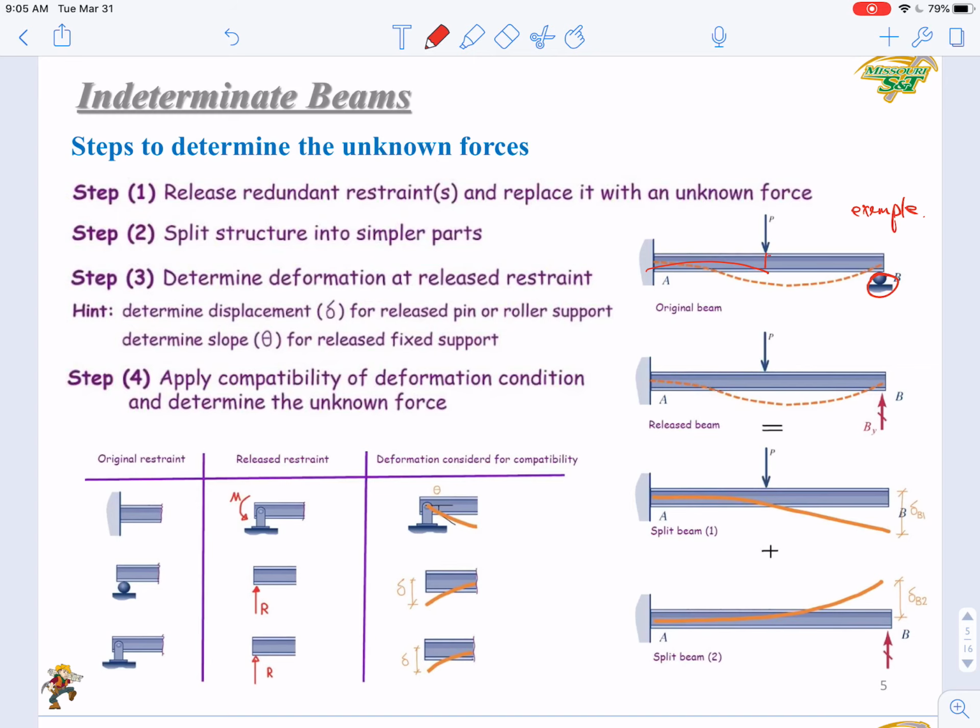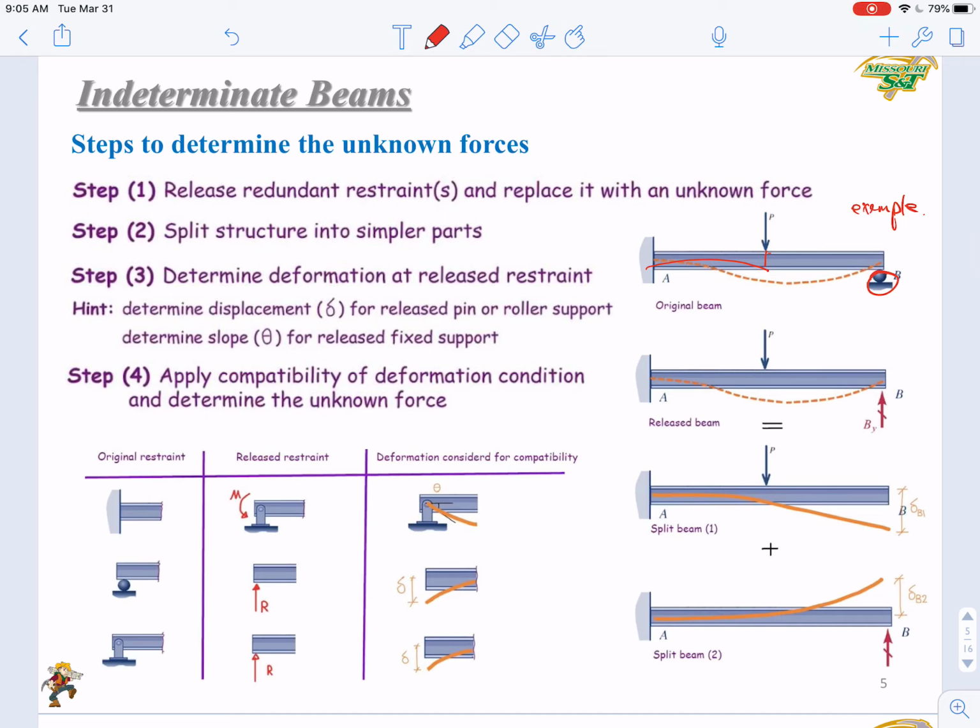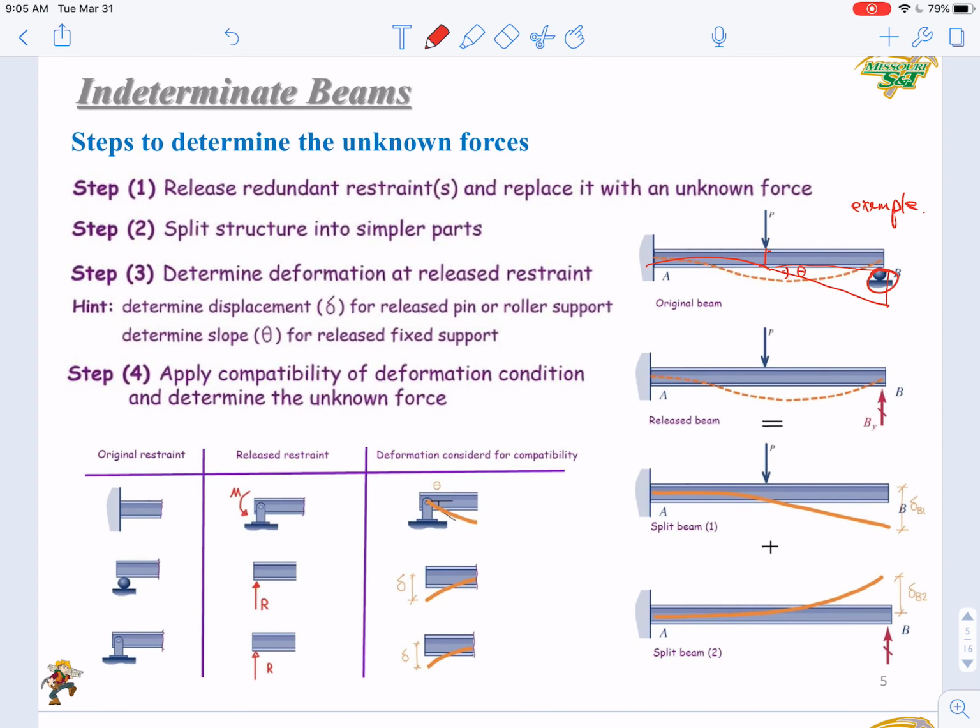Then this second part will be keeping straight. So you will get an angle. So you just calculate the slope at this point. So you can calculate even the deflection at the free end. Right? This is based on our previous 2 lectures. So you can solve any problem in this system. But unfortunately, here we have a roller B, making it an indeterminate problem. So you cannot solve everything just based on these 2 tables. You have to do more work.